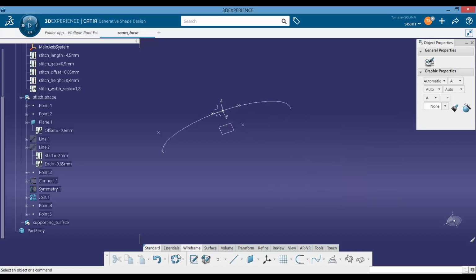Then of course we can grab our element and transform it from point to point. Why point to point? Because like this we always know the distance between elements. Technically we could in this case define it as well with a regular translation, but we would have to calculate how long this half is, and this parameter, so I consider it simply easier to manage to add this point on a new position where we want to keep it.